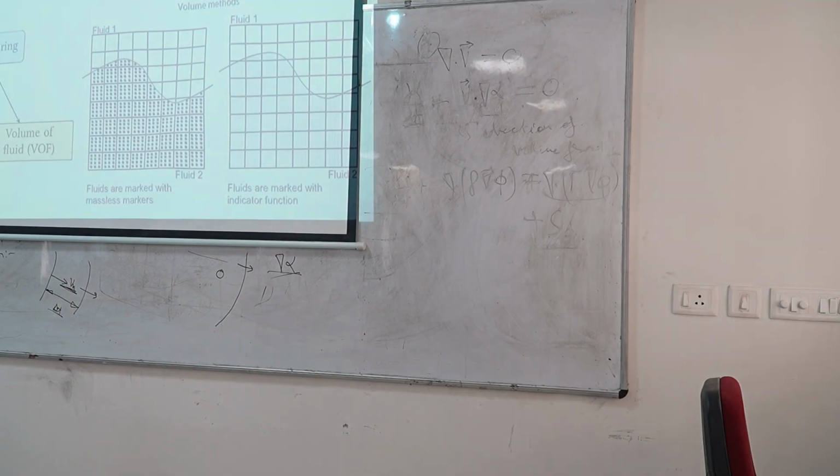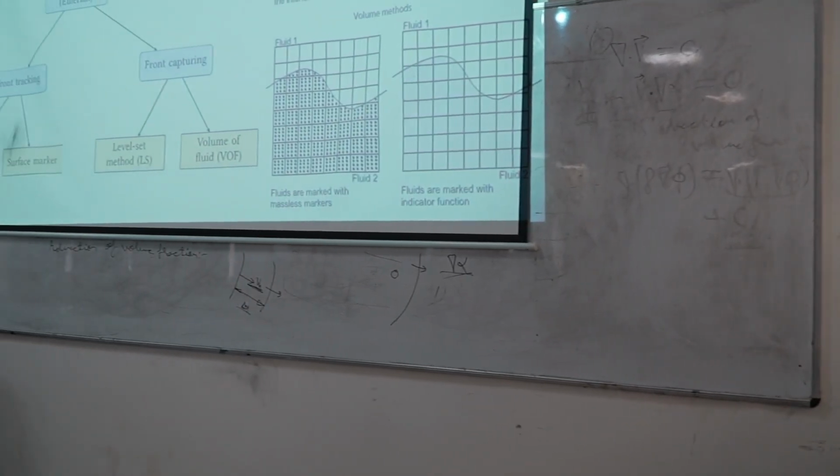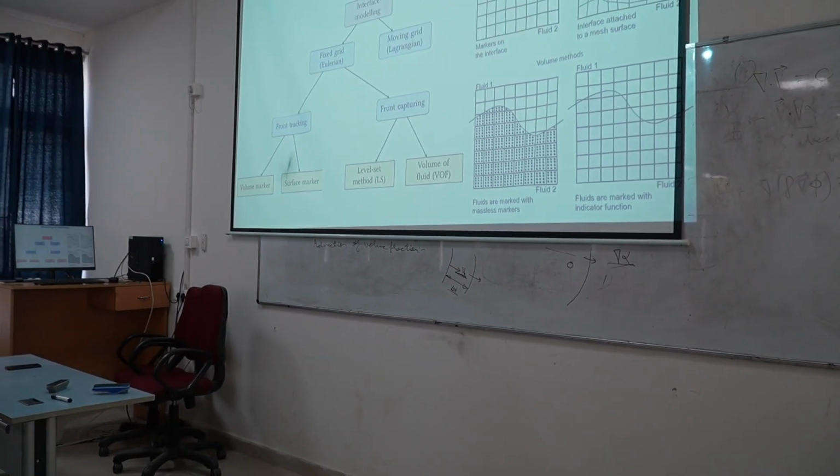Yes. Basically, this would mean that if I take a differential volume, the volume fraction within that cell should not change, as I follow the material particle. Yes, overall, if you follow a material particle, it should not change. But physically, how do you get this principle? This is the mathematical translation of this equation into physical words.